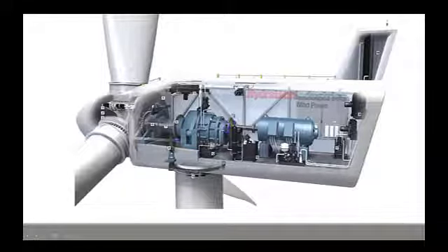and it's either a constant speed through clutches or some sort of variable transmission type of arrangement, so that the generator can run at a set frequency so that my electrical current is 60 cycles per second. Another way we can adjust the speed is by adjusting the pitch on these blades. And there's a motor here, and these blades are able to rotate, and these gears will cause that pitch to change, thereby affecting the speed.